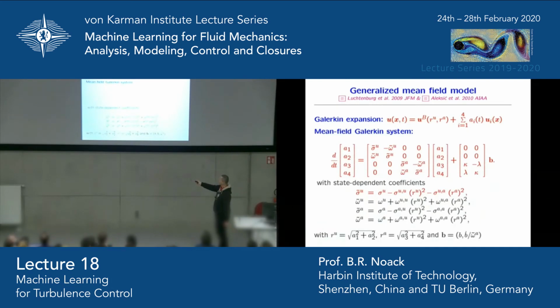Then there is a component which gives rise to the cubic damping. So without actuation, this growth rate will go to 0 by this amplitude increasing. But if you actuate strong enough, you also mitigate the growth rate. So if this term is as large as the growth rate, then this growth rate becomes 0, and von Karman vortex shedding cannot exist. Of course, the frequency depends on both energy levels, the other growth rates, and so on. But this is the key equation which you need to keep in mind.